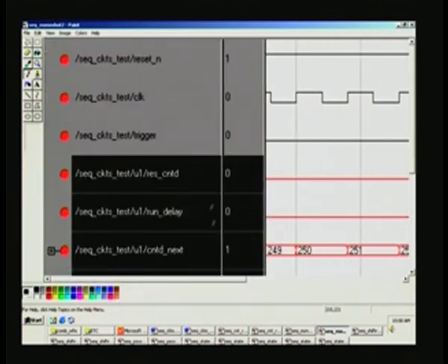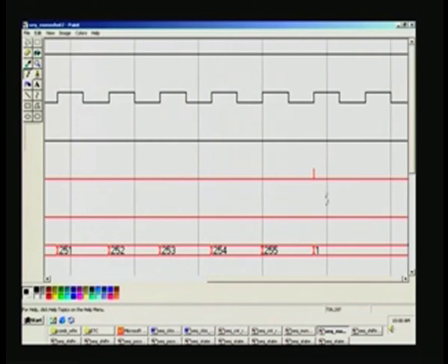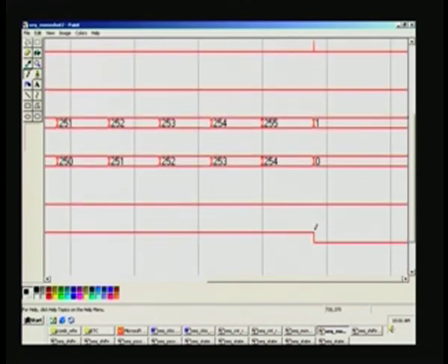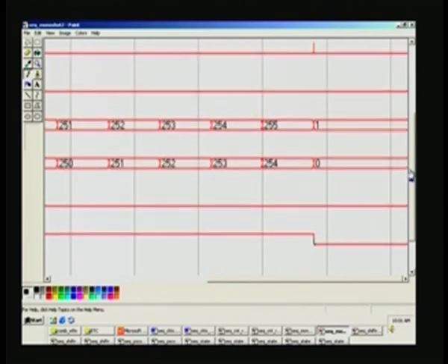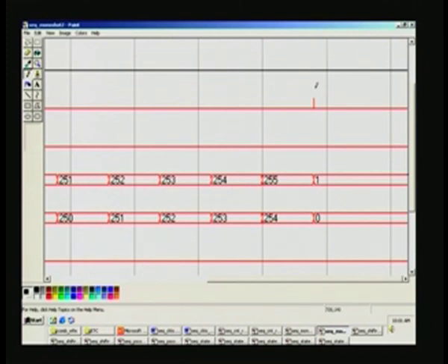So you can see this, it is activated here for a split second only, and the moment it is 255 this reset counter is 1, 255 is cleared to 0, that is what we have seen, and also you should have the output also 0, right, precisely at that point of time this is happening, right. And so as a designer you should be aware of all these things. One slight mistake in the code will make it topsy-turvy, right, and yes.